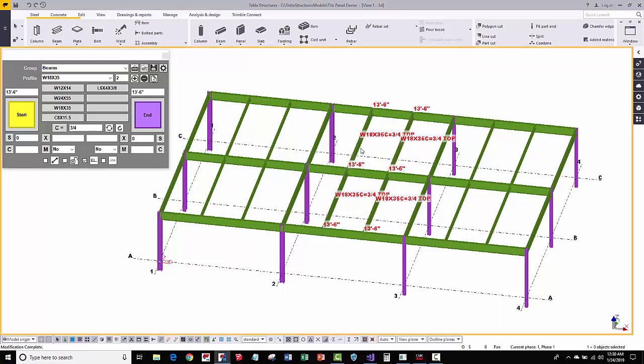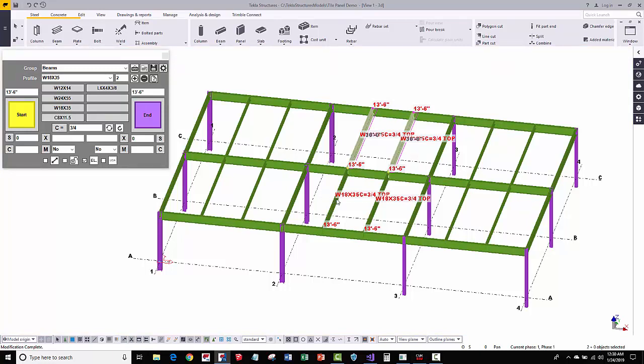Now what we can also do is set the connection code at the end of these. We know that these are all W18s and they're going into beams, so we might have a start and an end connection code here of W18-beam and then W18-beam. And we might want to write that to the user-defined attributes so we can use those for connection application or showing that on our drawings. Again, if we input these values here and we just want to modify something that's already in the model, we can just press the button next to that field and it's going to modify just that specific property.